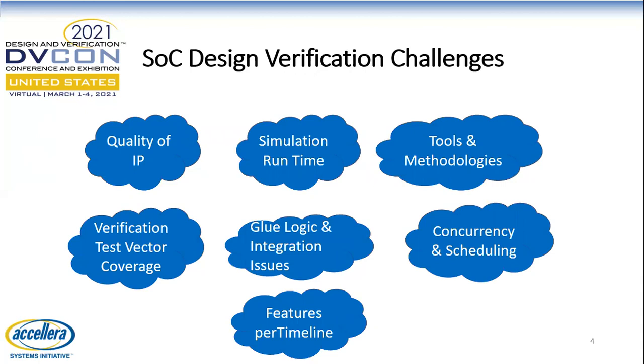SoC design verification challenges. There are many challenges in SoC verification. Some of them are mentioned in this slide. First one is quality of IP. If IP has bugs, the turnaround time of IP bug fixes can be more and it can affect SoC verification timeline. Next one is simulation runtime. Some of the SoC scenarios run for multiple days. Issues in long-running scenarios can drag SoC verification.